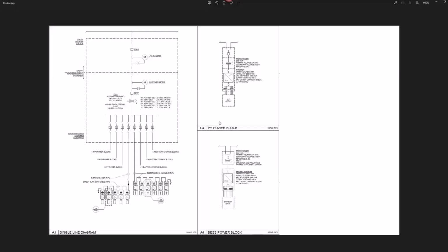Keep in mind that IEEE 519 is still sensitive to the system strength, which is the system short circuit ratio, measured at the point of common coupling, right? And starting from IEEE 2800 and 1547, short circuit ratio, which is the system strength, is no longer in the standard or in the criteria picture. So that's a big change to the applicability of 519 and 2800 and 1547.